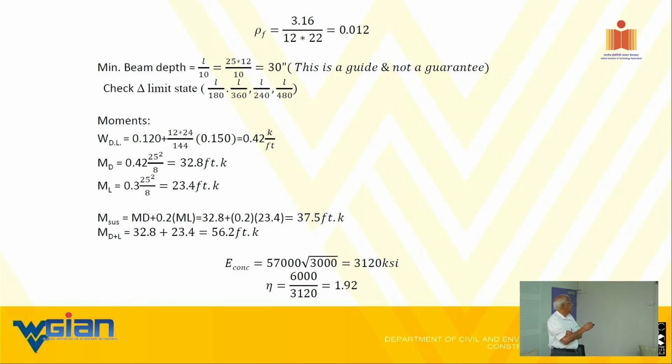Okay, so here you have the dead load there. WL squared over 8 is a very simple case, and you have a live load there, and then the 20% of the live load moment is what we are talking about as a sustained value. So they are accounting for, if you remember that slide 155 or whatever I showed you, he was asking me a question about the recovery.